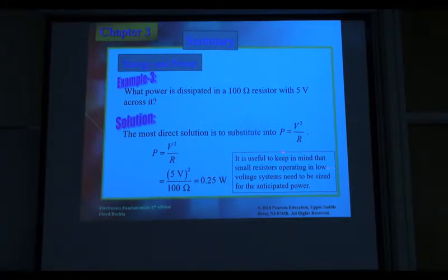So the key we learned from here is when you design a circuit, you need to use all the tricks we learned here to calculate the potential, right? The power will be dissipated on the device. For example, if this one is very big, then you need to choose the physical size that is appropriate for this one. Otherwise, you're going to be in trouble. If this one equals 0.25 milliwatt, that is too small, so you just put the resistor, that's fine. As small as possible, that's okay. Does it make sense?